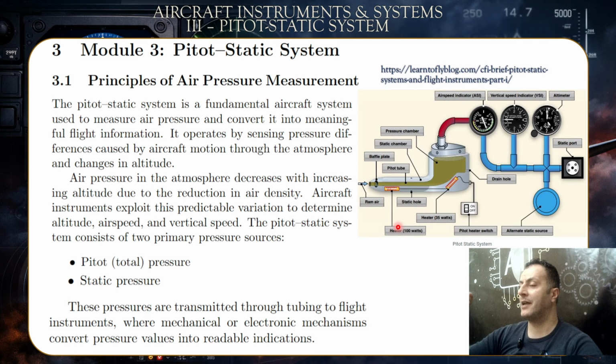So you would be getting an overspeed reading while the aircraft is stalling. And this appeared on that flight, I don't remember which one, a conflicting reading. You had an overspeeding indication, and then the stick shaker. Why?